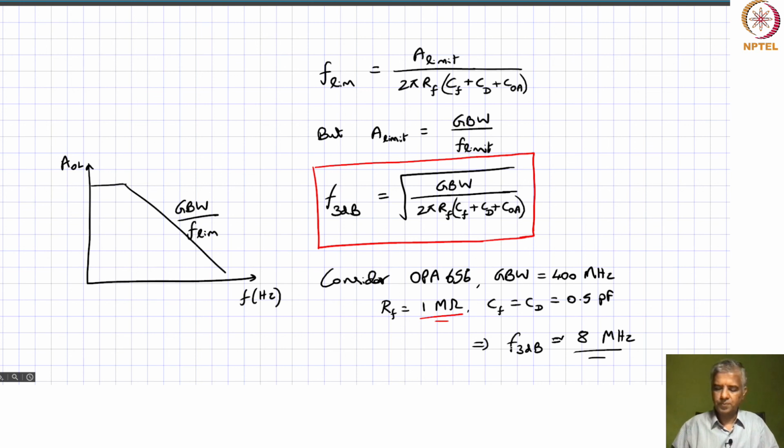So you essentially have these op amp based transimpedance amplifiers where we once again play a trade-off between the maximum gain that you want to achieve from the transimpedance amplifier versus the bandwidth that you want to maintain in doing so.